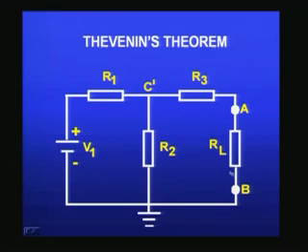So now let me take an example of a circuit which has three internal resistors, R1, R2 and R3, and RL is the external resistance between the terminals A and B. You have only one voltage source, because to start with the example will be very simple, with just three resistors connected as shown in the figure. Our job is now to find out how to solve this using Thevenin's theorem, so that we should be able to obtain ultimately an equivalent Thevenin's voltage and equivalent Thevenin's resistance, which will replace the voltage source V1 and the R1, R2, R3 combination.